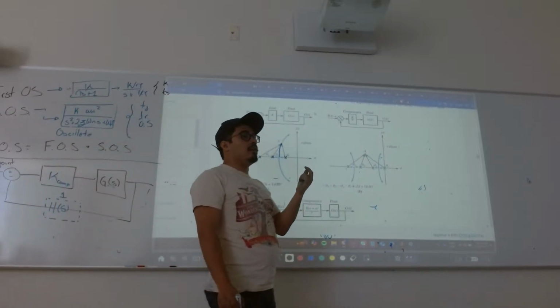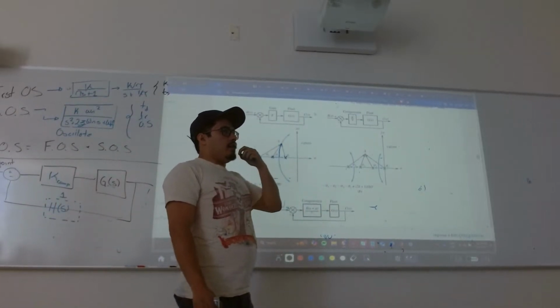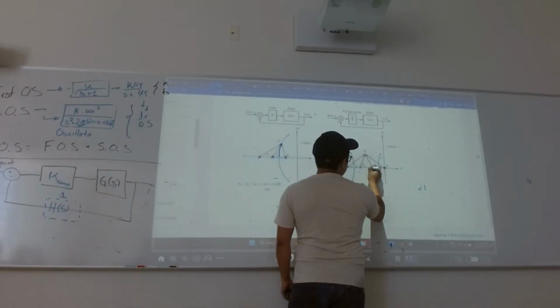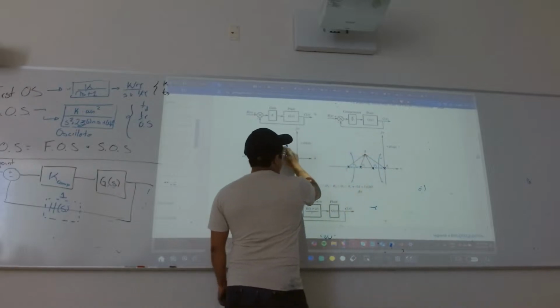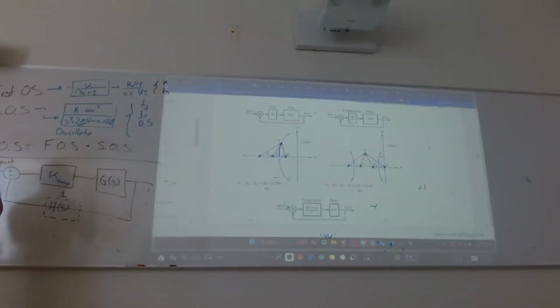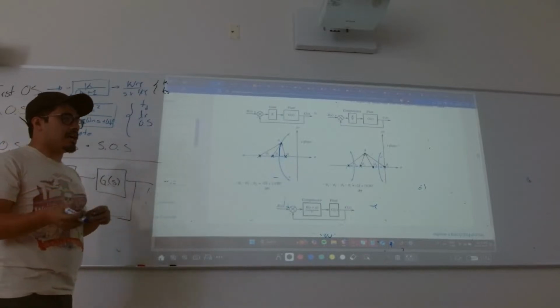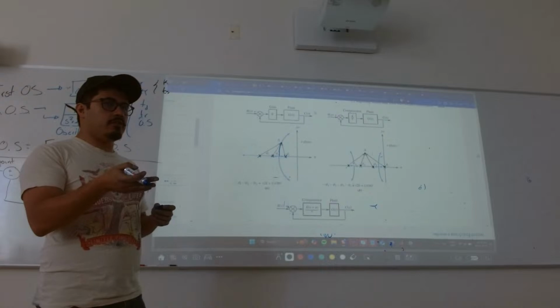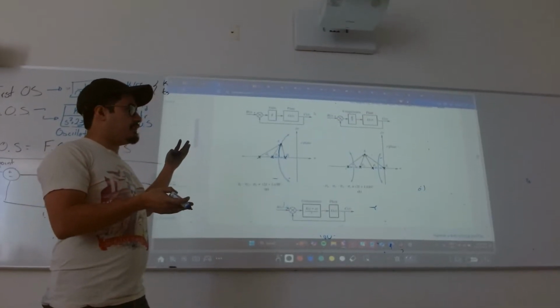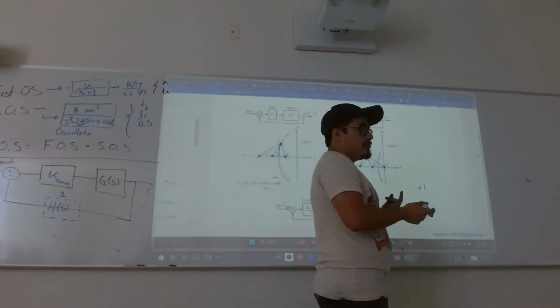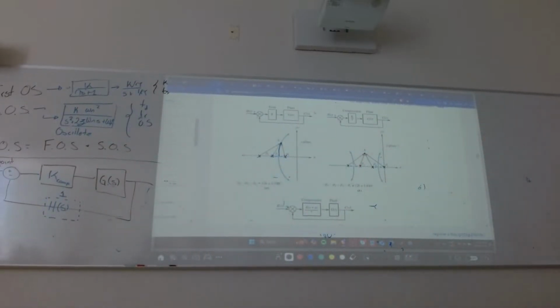The integral part is what is going to be eliminating the steady state error. But that is adding another system, and the original behavior I had on the system is now unachievable, right? So the way the system was performing, just by adding the integral, is now unachievable, which means I need to introduce this zero without, or at least in this kind of problem, without changing the original system, because that's the requisite.